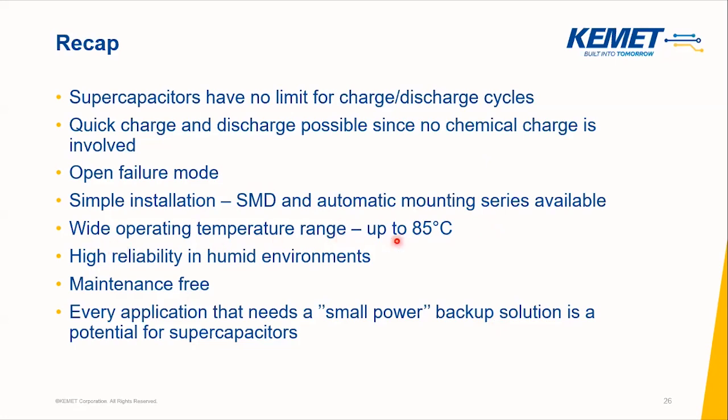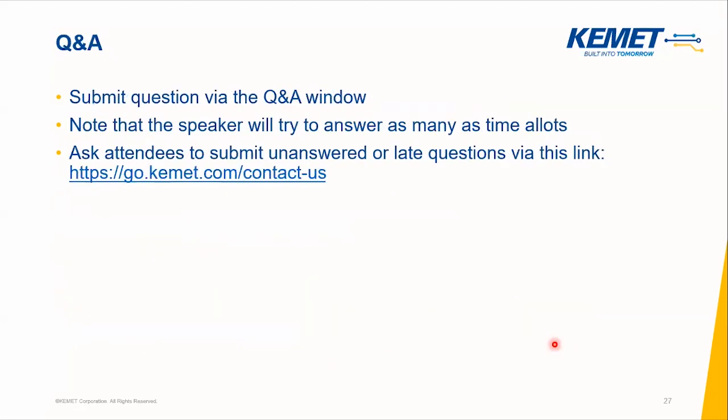Wide operating temperature up to 85 degrees, high reliability in humid environments, as I mentioned, because we also have a special design. It is maintenance free, and every application that needs a small power backup solution is a potential for supercaps. But always keep in mind, supercaps have high power densities, while batteries have high energy densities.